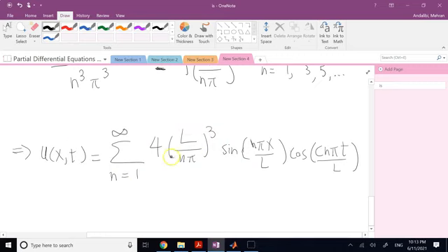The rest of them will have what? A very small contribution. Okay, it's just the first few modes of vibration that are the dominant modes of vibration. You clearly see why, because as n goes up, this coefficient, which is the weight of that mode shape, is going to go down so fast.